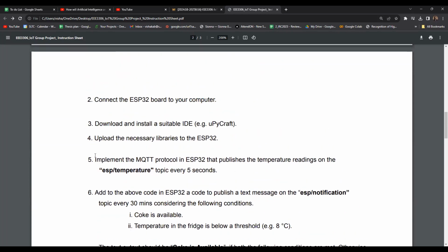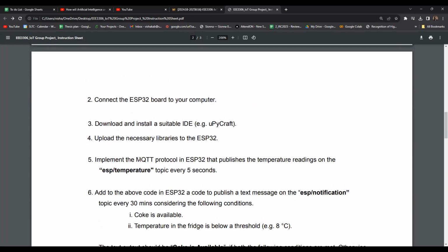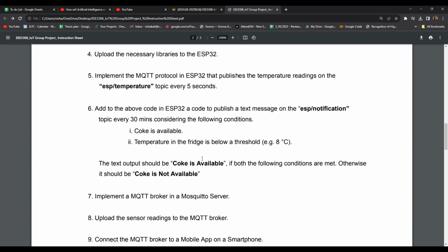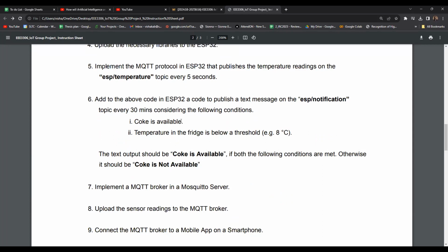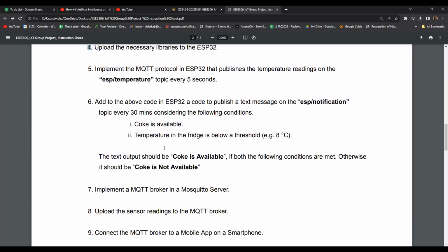I will explain all this about the MQTT protocol once I come to that section in the theory class. So up to the point where you can run some code in the ESP32, you can complete the tasks. Afterwards, you need to learn about the MQTT protocol and establish it in our ESP32s, and then do the protocol based transmission, and that data will be received by the MQTT server. This MQTT server will transmit the data to the necessary users. So that is basically the necessary work to be done. Up to now, I think you can do up to step 4.